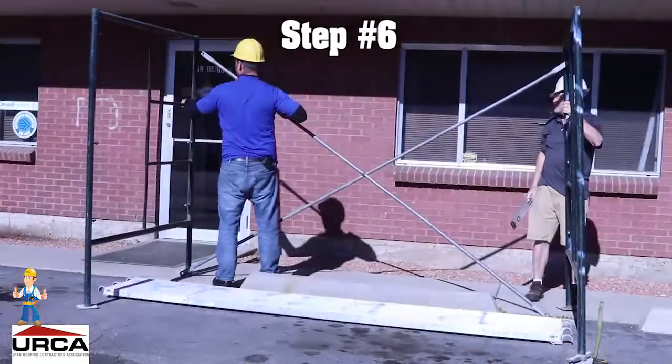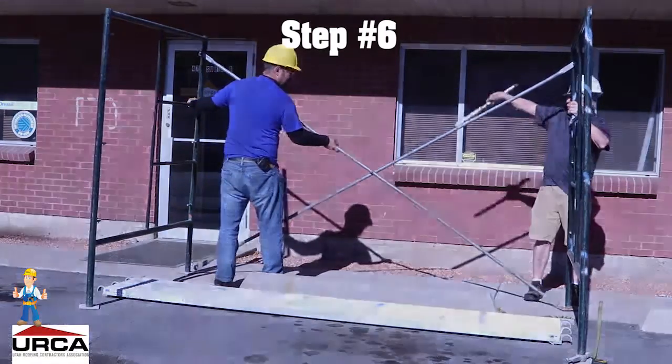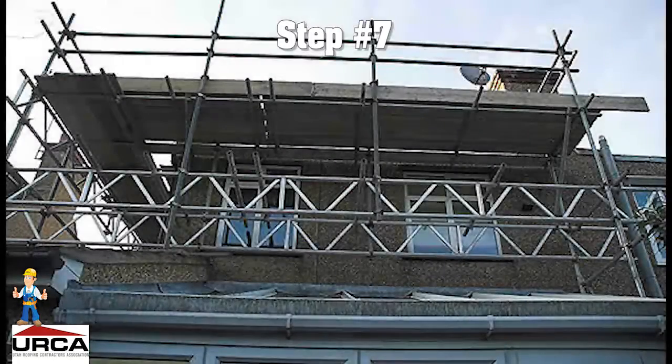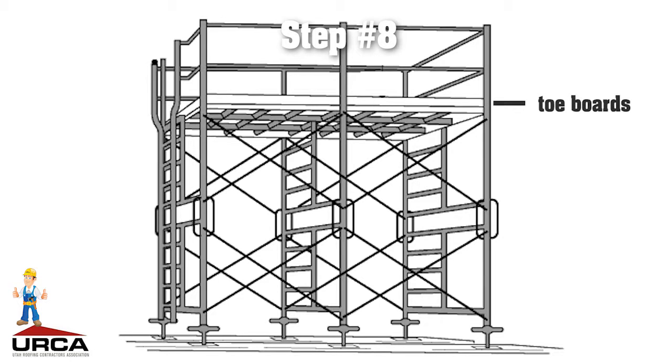Step number 6. Install guys, ties, and braces according to the manufacturer's recommendations. Step number 7. When platform units are abutted together to create a long platform, each abutted end must rest on a separate support surface. Step number 8. Once erected, provide toe boards on all railed sides to prevent falling object hazards.